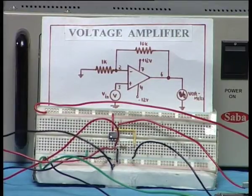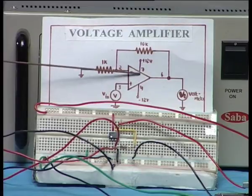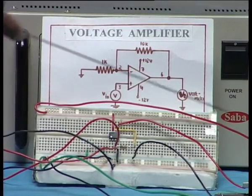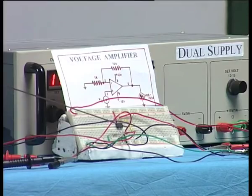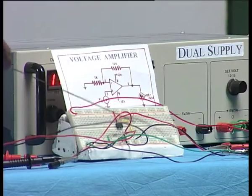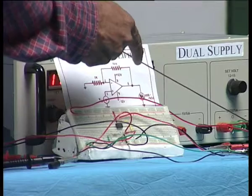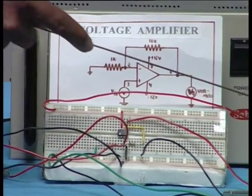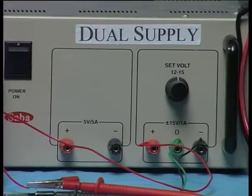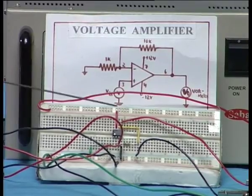So if you look carefully at the op amp, there is the op amp 741, and you can see the 7 terminal is for the V plus, that is connected to the red wire, and the red wire goes to the plus of the dual supply. Similarly the pin number 4 is connected by a small black wire to the negative terminal, and this black wire goes to the negative V minus of the dual supply, and the green wire is connected to the ground of the voltage source. R1 and R2 are seen, and it is very similar to what you saw in the simulation on the screen.